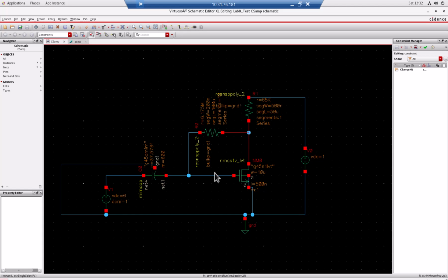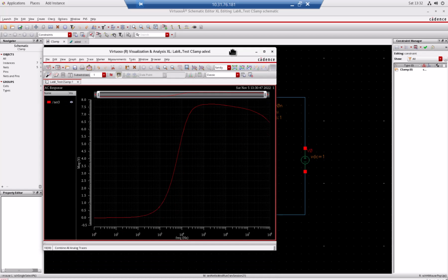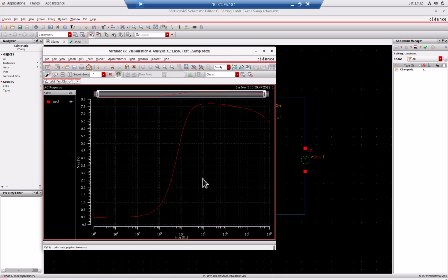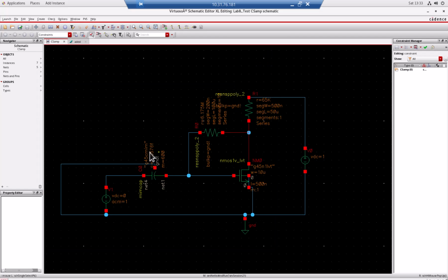So in order to increase the gain at low frequency, I need to increase the size of my capacitor. But then later you see the layout is going to be very large, right? So my design is okay if I'm only interested in the frequency of, let's say, 100, sorry, I said it wrong before also, 100 kilohertz to 1 megahertz, then it is okay. If you're interested in amplifying this region, then it means you need to have a very large capacitor or a very large RG or R0, and that your layout area will increase a lot.